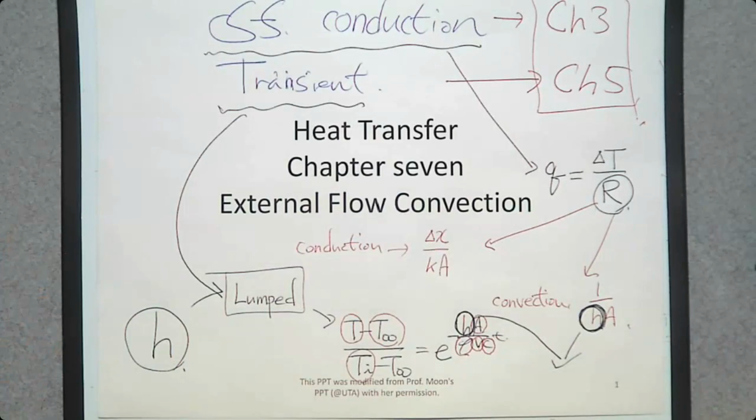The point is, when we talk about material properties such as density and specific heat, are they constant? Not usually. Usually they are variable. They change with temperature. For example, when temperature goes up, the density of gas goes down, and for specific heat, as the temperature goes up, specific heat goes up. So usually, when you want to determine these thermal properties, you just need to determine the average temperature and evaluate those properties at the average temperature from a table. So as long as you have a table, you can determine them.